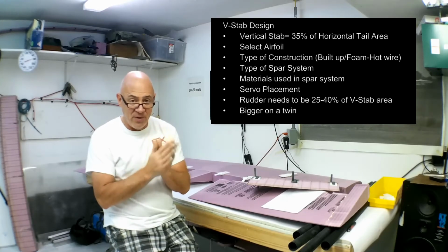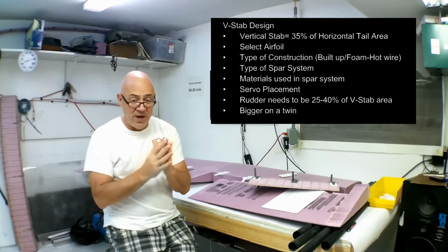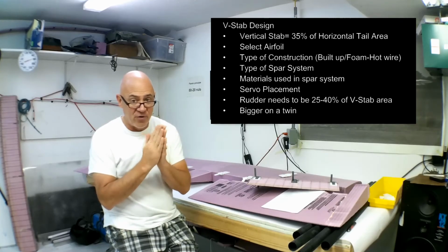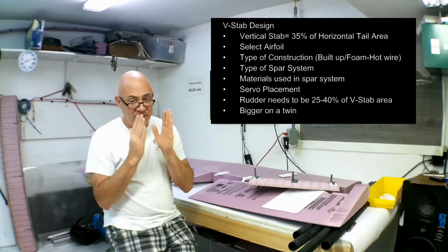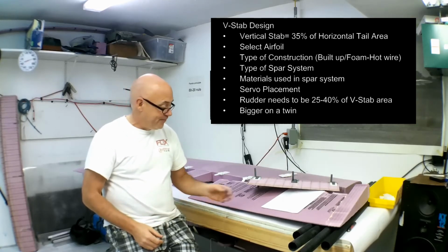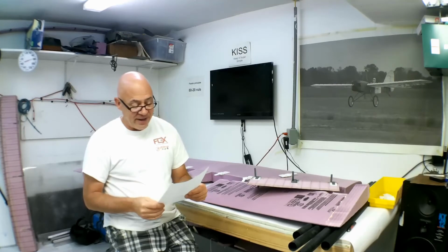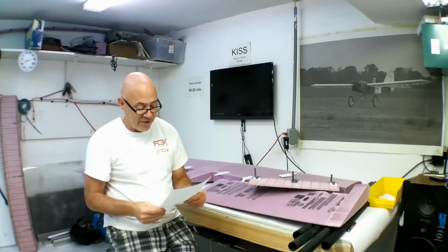Do not build a multi-engine B-25, B-24, B-17, B-29. Do not build a multi and only have 15 degrees of rudder. You want 35 degrees, maybe 38 degrees. I don't know if any went to 40, but you want a lot of rudder movement or it's pointless on a twin. It burns me when I see planes crash. You see them going over and there's just a little bit of rudder going the other way, and I'm like, what the hell? They didn't have enough rudder.